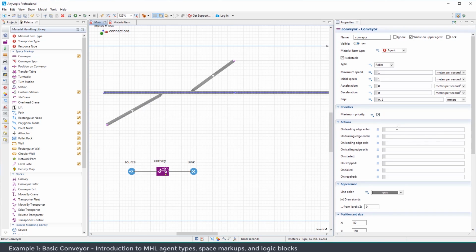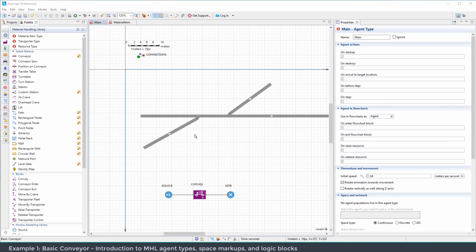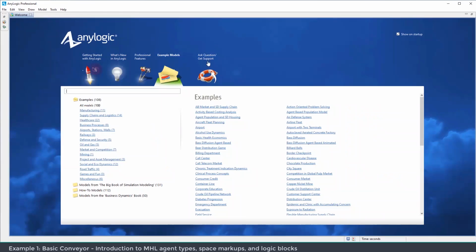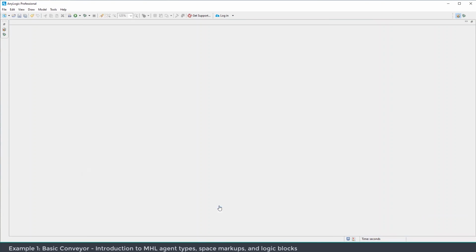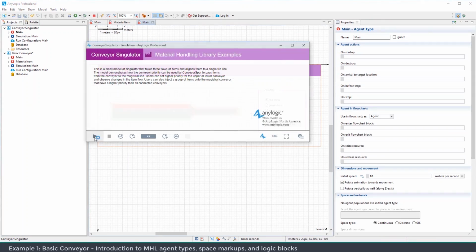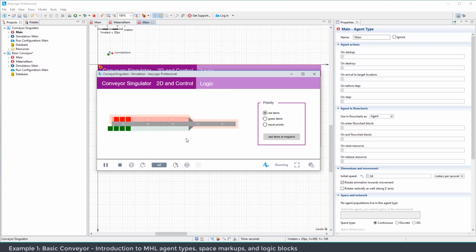Changing the priorities of a main conveyor that only has one merging branch does not do anything, and the main conveyor is treated as a higher priority. However, if 2 branch conveyors with incoming flows are connected to the left and to the right side of the main conveyor at roughly the same offset via a conveyor spur element, AnyLogic will compare priority values specified for both conveyors. The material items incoming from the conveyor with the higher priority value will get preference.